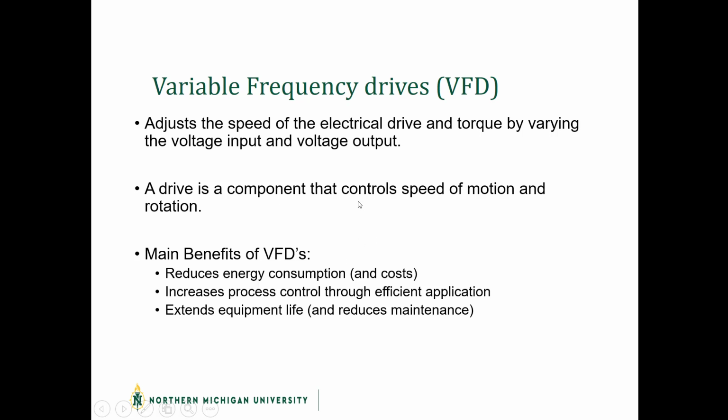What this basically means is that if we don't have a VFD or any other means of controlling a drive, when a piece of equipment turns on, say a motor, that motor is going to operate at full capacity because that's what it's designed to do. As soon as it turns on, it's going to talk, through the electric current, to the switchgear to say, I need this much power, and it's going to give you that much power. But if it only has to operate at, say, 50% capacity, the VFD is the thing that can control how much is actually needed to maintain that motor in operation. So if we don't have to operate it at full capacity, then we don't, and the VFD controls that.